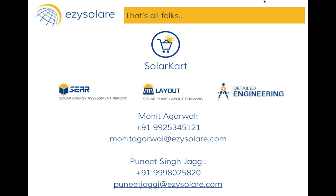From time to time, for certain limited periods, you have got specialized instruments that you can take on site and measure some more losses. For example, degradation of a solar panel can be measured by using a PV IV curve tester on site, which is an equipment costing about 3 lakh rupees that you can buy.